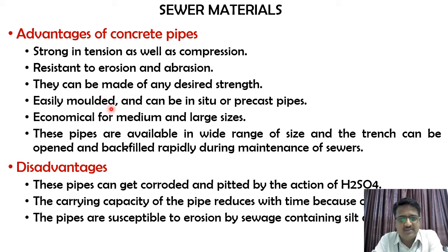So these can be easily molded and can be in situ or precast pipe. Easily molded in the sense that, based on the diameter of the pipe, we usually have particular molds in which the reinforcement bars are first put up, and then the concrete is laid. After a particular period of time and proper curing, it can be used as a pipe material.